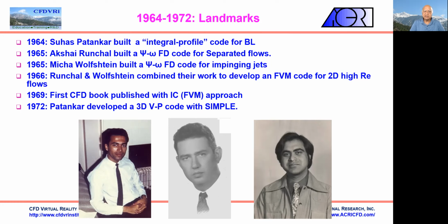What Patankar and Spalding did was simplify this profile and generalize it by saying we can build any profile by piecewise linear segments. So this was called the integral profile method. It was not quite finite differences. It was an analytical profile made with piecewise linear segments. Nonetheless, it led to algebraic numerical solutions like the finite difference scheme. However, this method could not be used for separated flows or flows with high streamline curvature or strong pressure gradients.